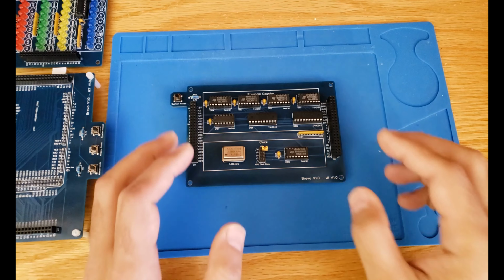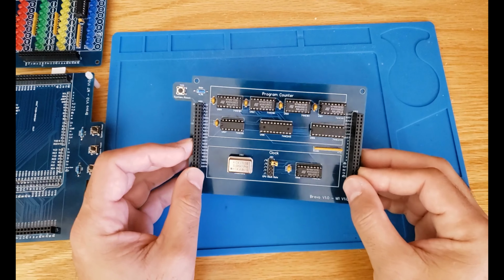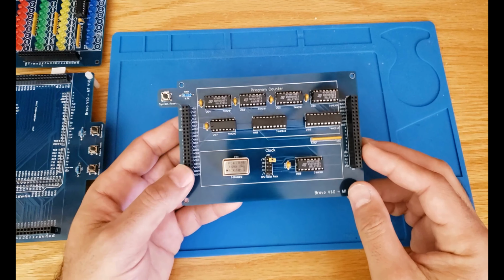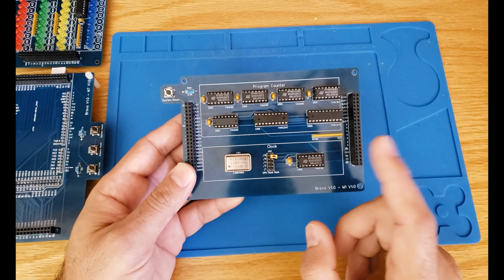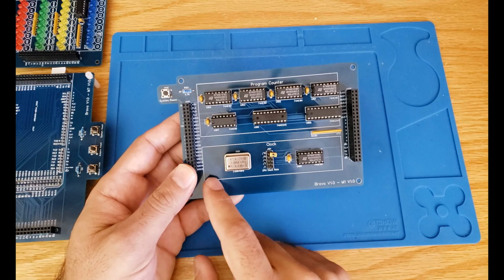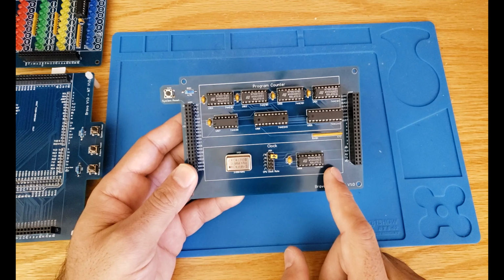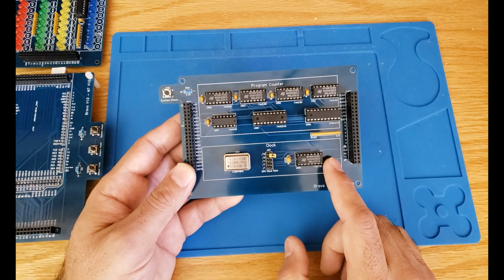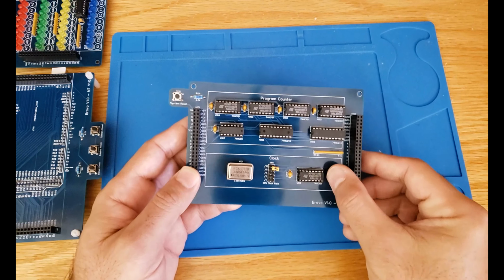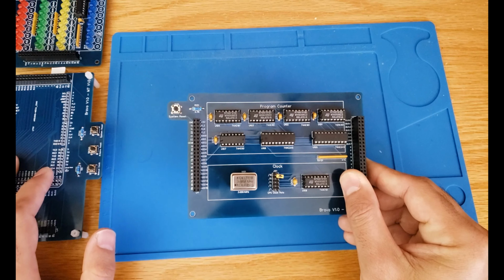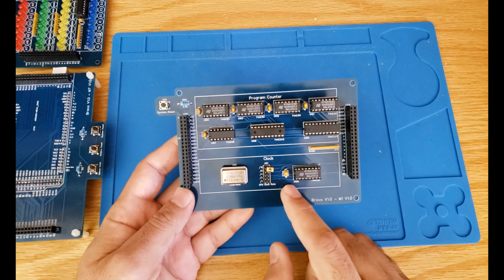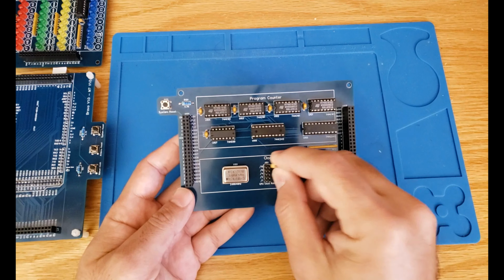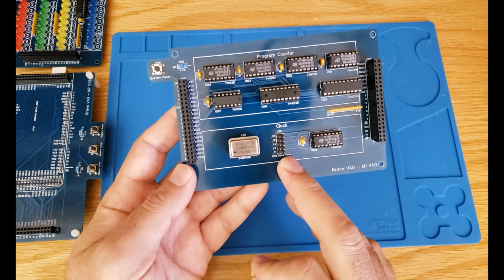All right, I guess we are ready to test our program counter. Just before we start the process, there is a point that I would like to mention, and this is about the clock module. Remember that we are not using this original clock module for the tests here. The reason is that this clock is running at really high speed, and during the testing, we will be using the clock from our Arduino shield. Therefore, we just disable this clock for now until we have a complete build, and then we could re-enable the clock. So in order to do that, you just have to make sure there is no jumper connecting those pins.